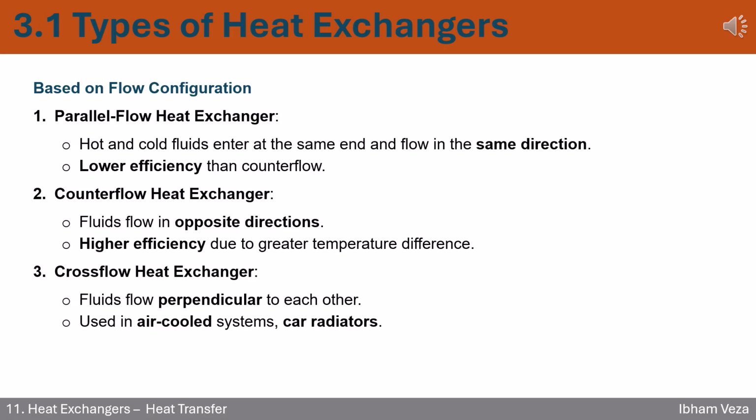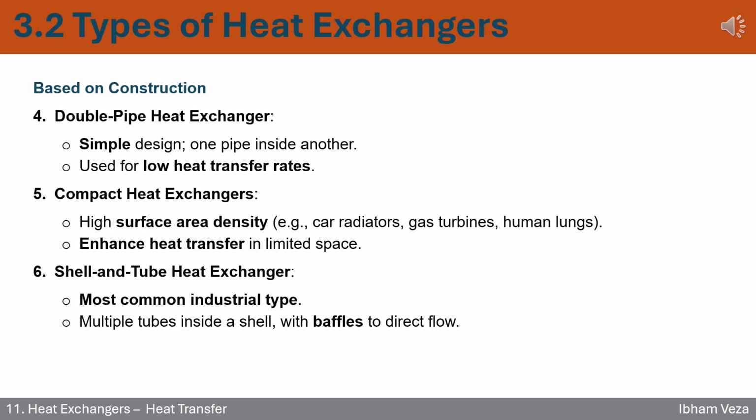Each type has its own strengths, but the rule is simple. Counterflow is most efficient, parallel is simplest, and crossflow is very practical when space and airflow matter. By knowing the flow pattern, you can predict performance before even touching the calculator.